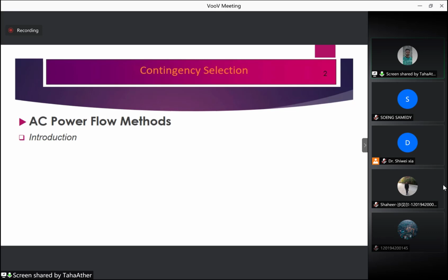Most operation control centers that use an AC power flow method use either the Newton-Raphson or the decoupled power flow method. These solutions are used because of their speed of solution and reliability. The decoupled load flow has further advantages in that a matrix alteration formula can be incorporated into the simulation using the Jacobian matrix at each iteration.